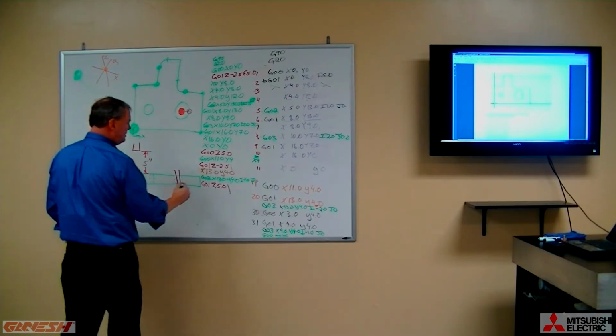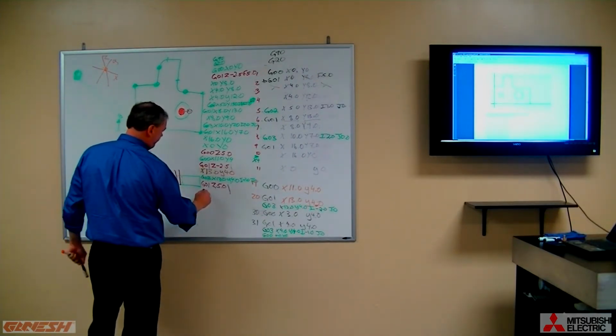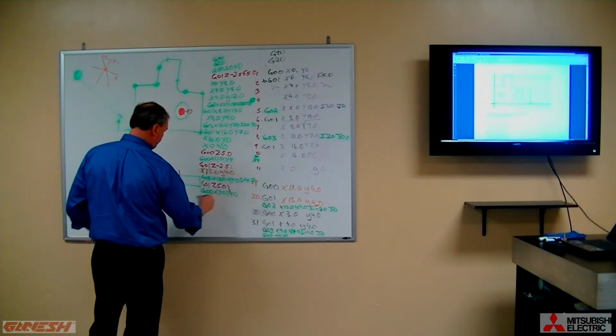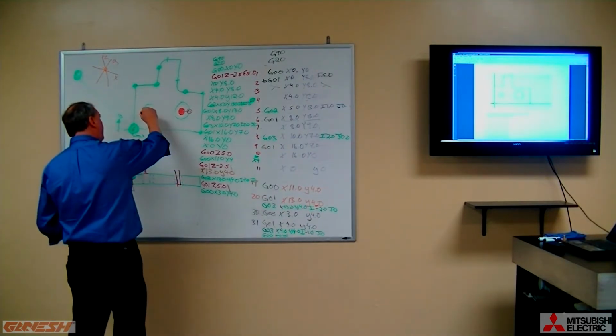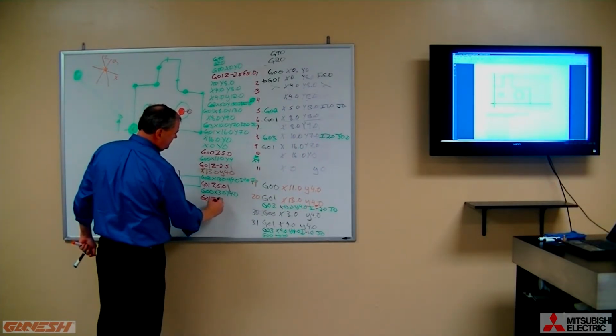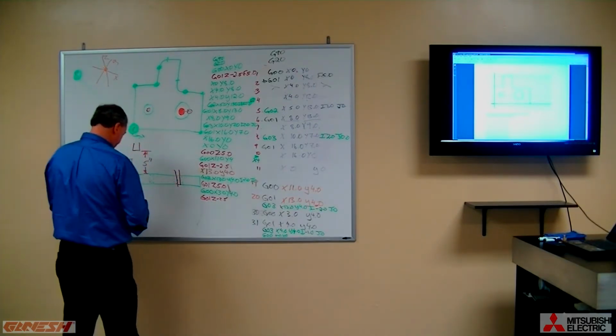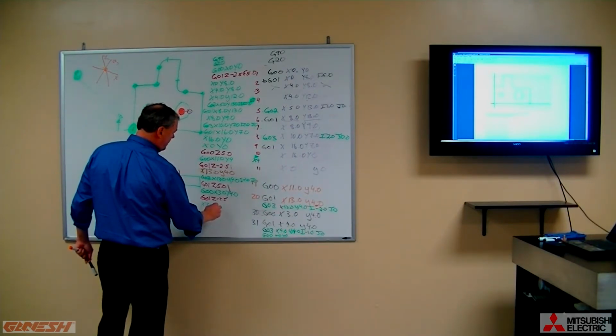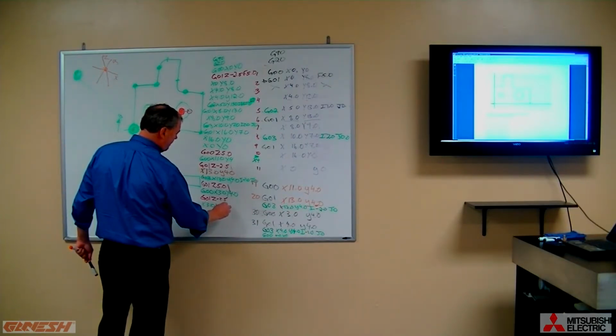So now we're going to go and say G00. Position over X3.0, Y4.0. Now we're going to bring our tool back down at a feed rate to the right cutting depth. G01, Z minus 2.5. And now we say X3.0, Y4.0. And now we